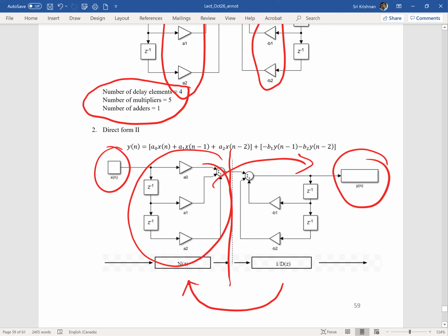One of the main drawbacks of digital filters is that because we have to implement them using delay, if the delay is substantial, then it adds up, and that makes the whole process quite slow. Whereas we don't face this problem in analog circuits because they don't have delay elements. The other thing we need to keep in mind with digital filters is the effect of word length.